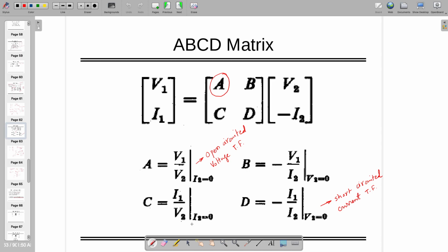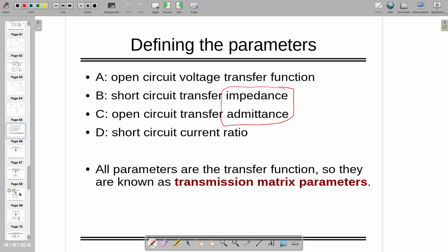So in that way these two are also transfer functions, but one is an impedance transfer function and one is a transconductance transfer function, or admittance. All circuit designers will not call this one admittance, but they are going to call it the transconductance transfer function. You can call it admittance right now, no problem. So any problem in this? No? All four parameters, right?